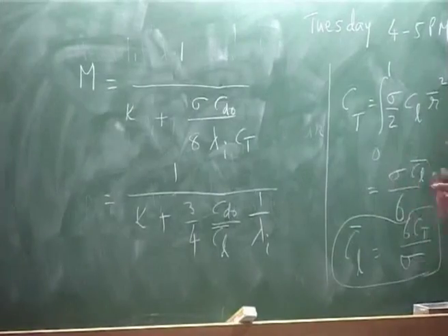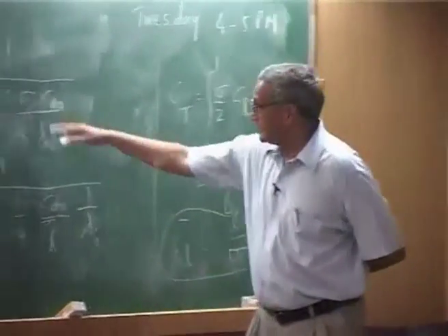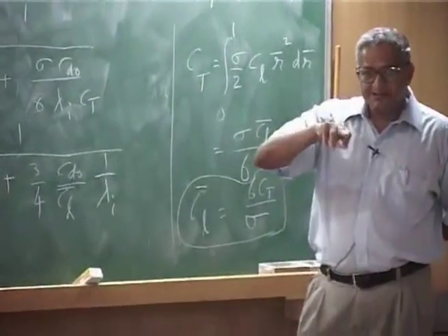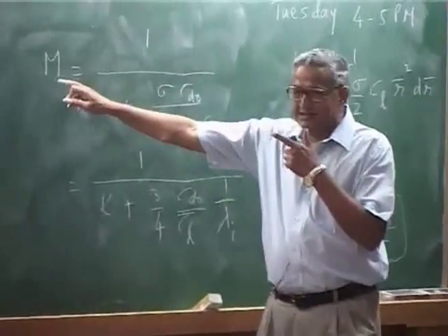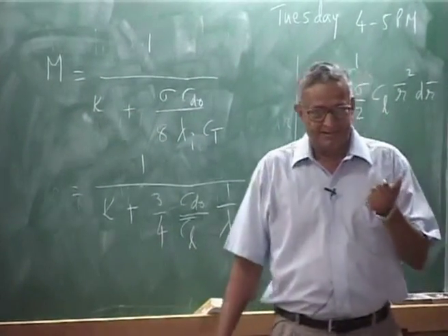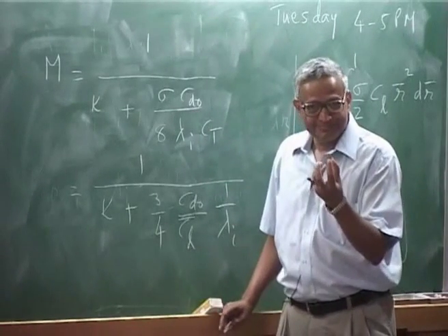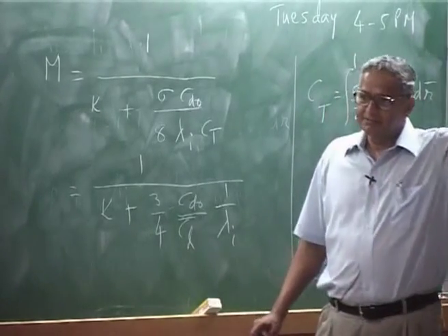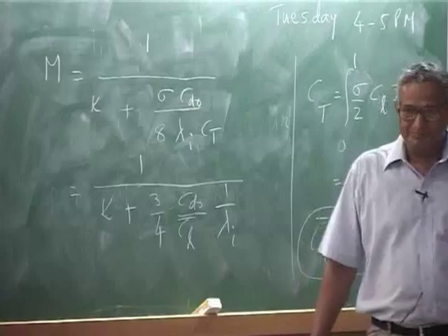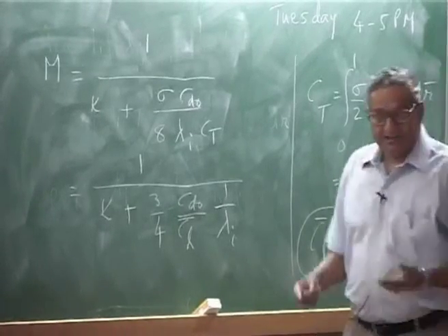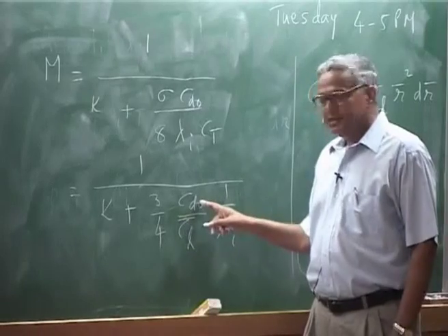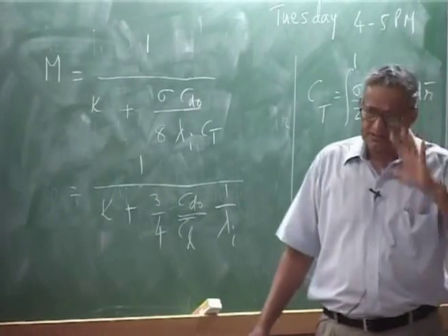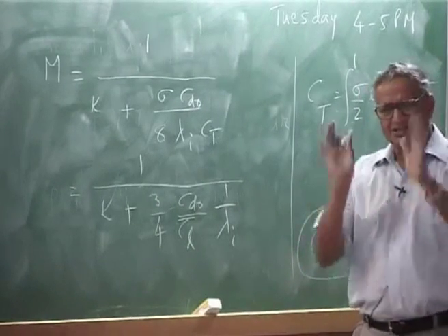Okay. See, these are all modified expressions. Here sigma does not appear, that is the solidity does not appear. Earlier we said that if you want to increase the figure of merit, you reduce sigma, but if you reduce sigma, your mean angle of attack will go up, Ct by sigma. Now, in this form, you have CD naught, which is the sectional profile drag, CL bar is sectional lift coefficient, you can take it, mean value, which is a sectional lift.